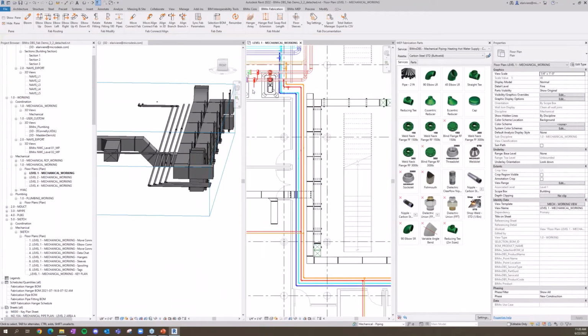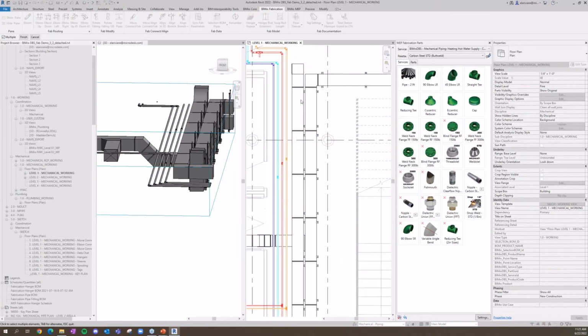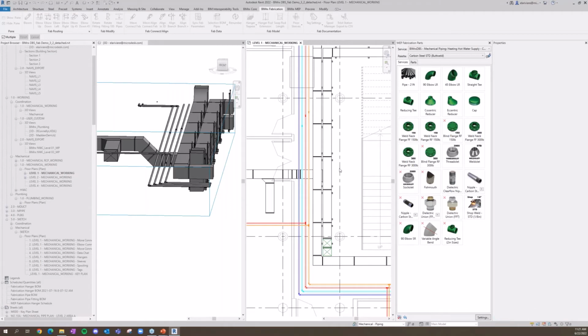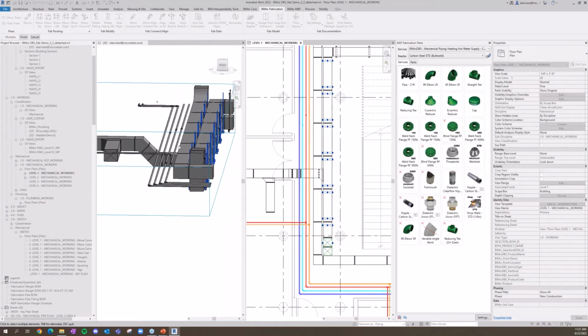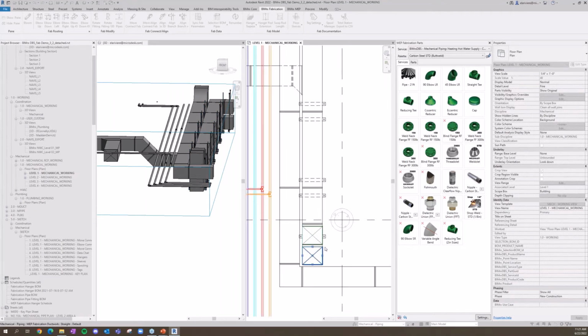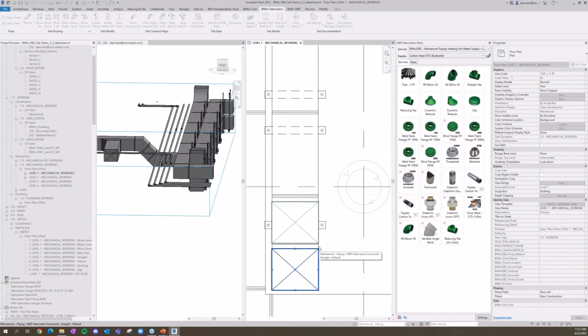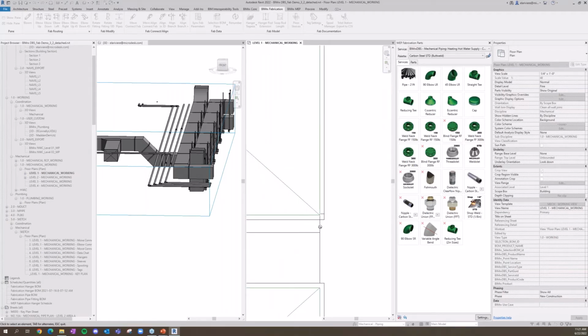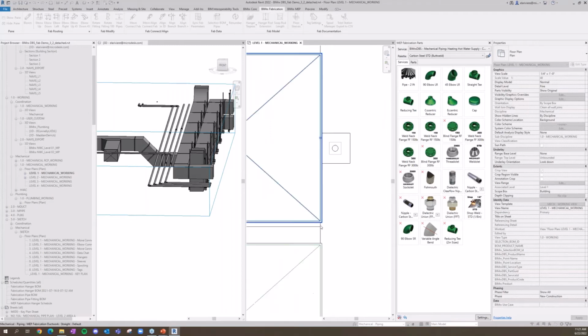Well, we actually have a trapeze command, and we've updated that trapeze command to be even more intelligent. So that hanger trapeze command that I have now allows me to go ahead and grab all of these trapezes, click finish for my selection, and then I can go ahead and choose my host side. So I'm going to say I want to go from that maybe lower element down here, and I'm going to get real close so I can make sure I'm selecting the one I want.